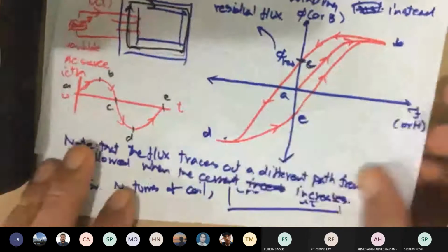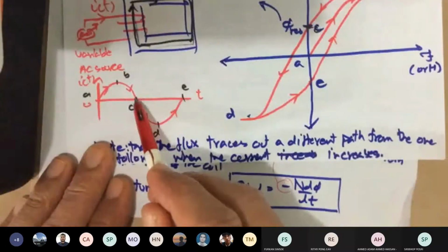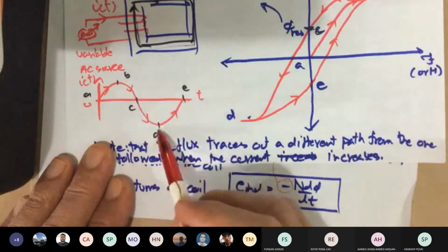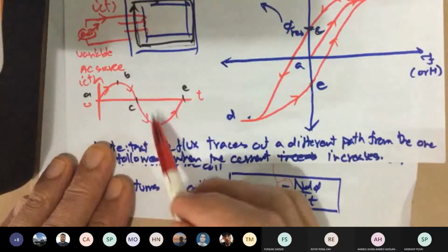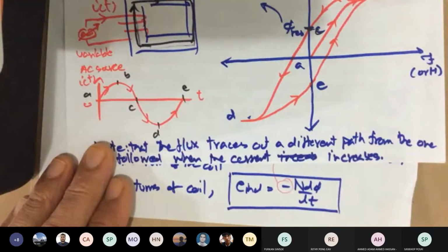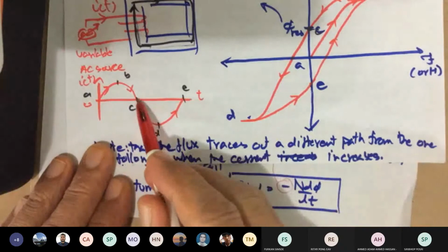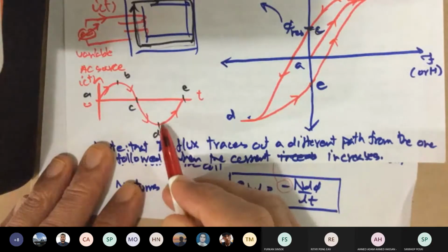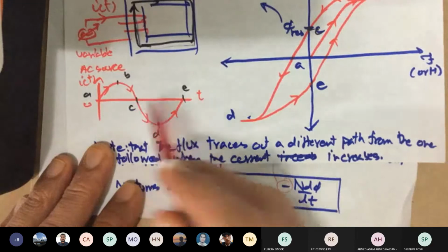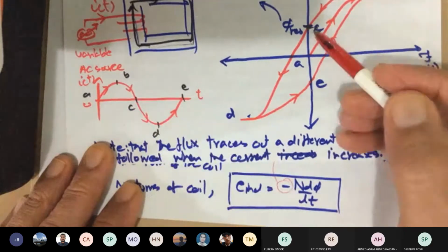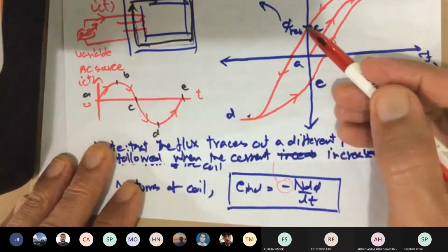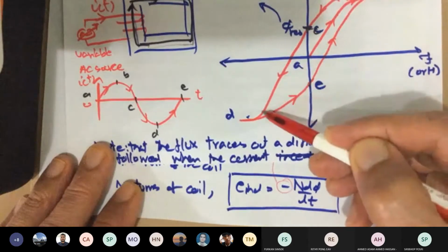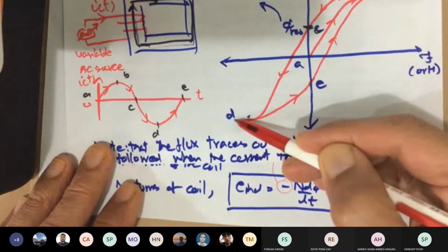Now we're back to point C. The current now becomes negative, sinusoidal. C to D, you're decreasing the magnitude in a negative manner, right? From 0 amps, now it's going to be negative some number, let's say negative 10 amps at peak value. So your flux would reverse direction here, and then it's going to try to be linear, and then saturates at D at the peak.